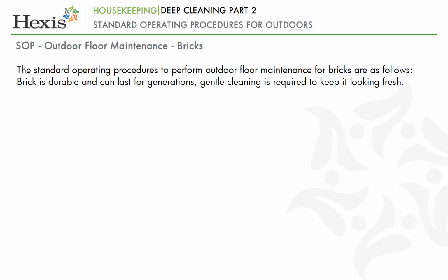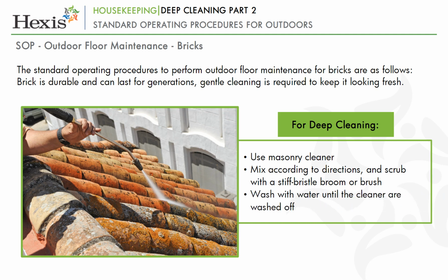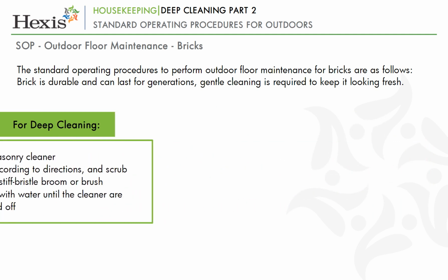Although brick is durable and can last for generations, gentle cleaning is still the best way to keep it looking fresh. Use masonry cleaner. Mix according to directions and scrub with a stiff bristle broom or brush. Wash with water until the cleaner is washed off.